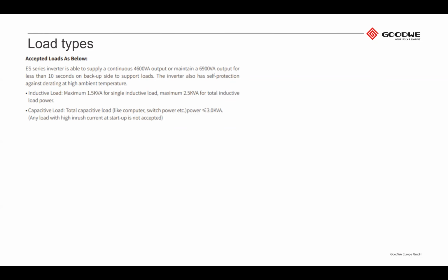So this also counts for booster pumps. A lot of customers these days have water tanks and pressure booster pumps, and they're normally the cheap kind. And the cheap kind, unfortunately, does not have a good power factor. The capacitors are normally also too small to start up the motors properly. They have all different kinds of problems. They start a bit at full speed, ramp up against the high pressure, which causes a higher demand as well to start up. And all of these factors cause higher inrush currents and cause the device to trip as well.